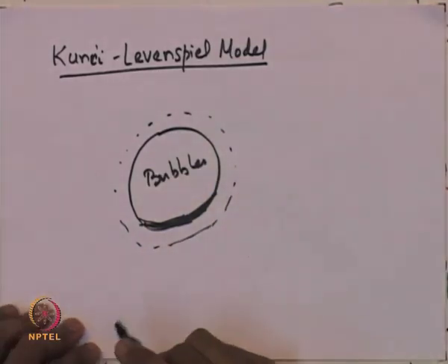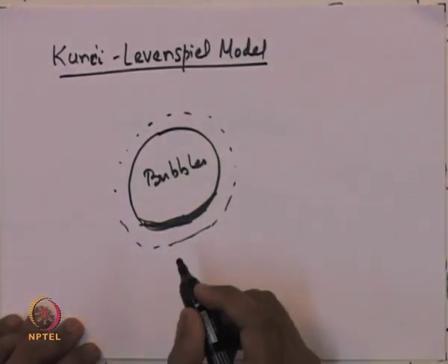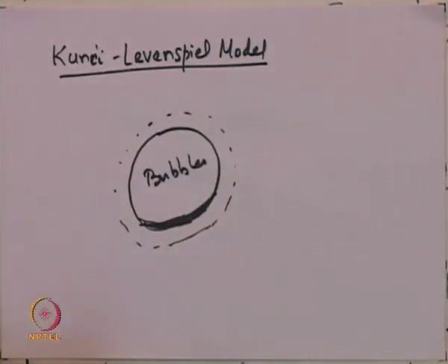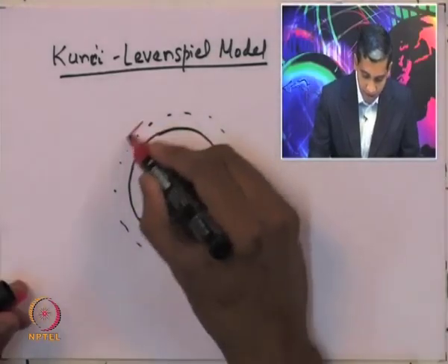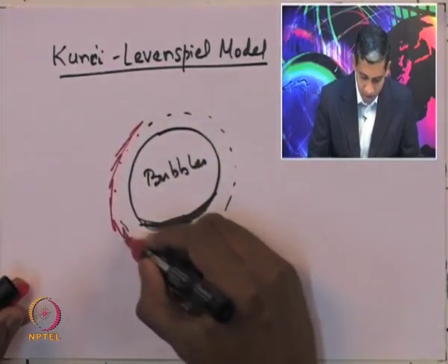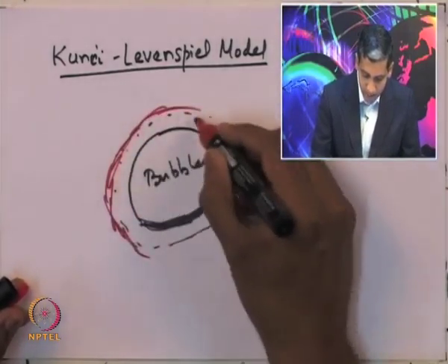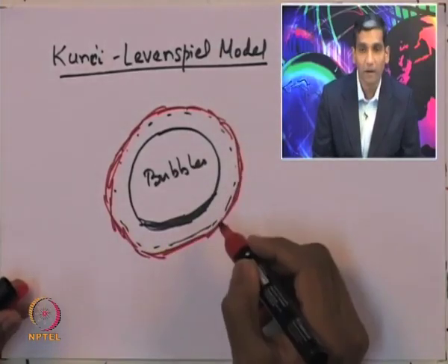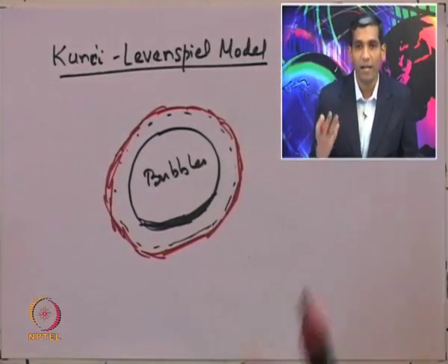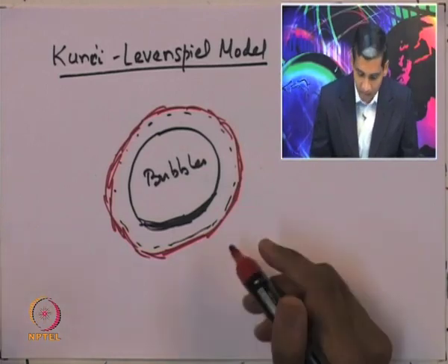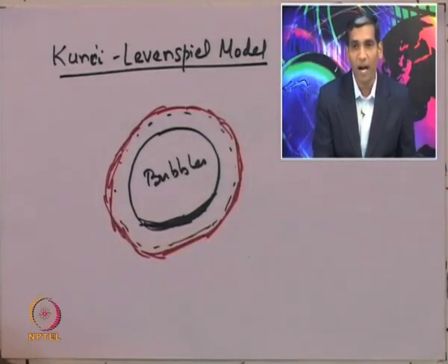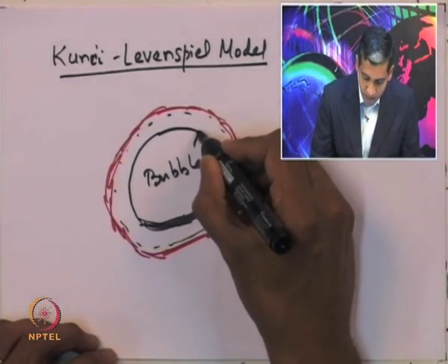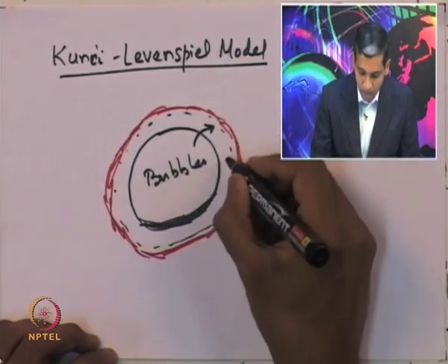There is a phase called the cloud phase, and in this cloud, there are some particles present. Around the cloud is the phase called the emulsion phase, which also contains lots of particles, and the emulsion phase has essentially the same porosity as nearly the porosity of the resting bed. Therefore, the mass transport process which occurs is that the reactant species are transported from the bubble to the cloud phase.